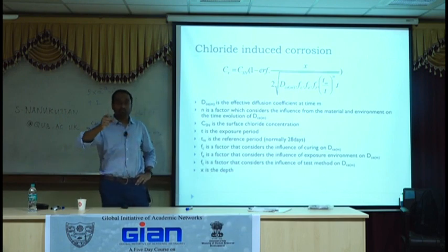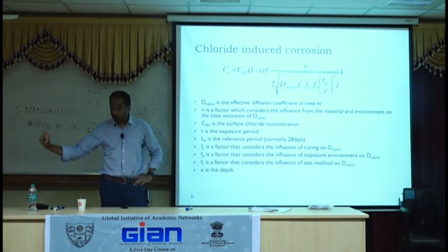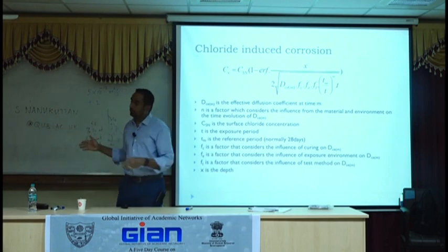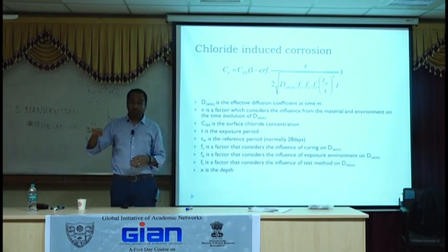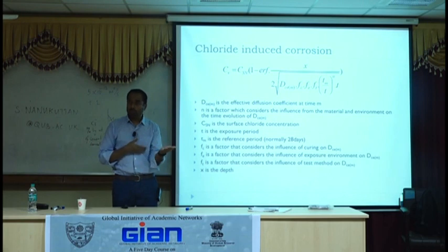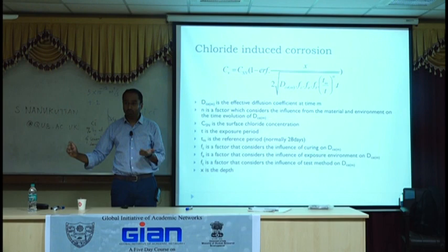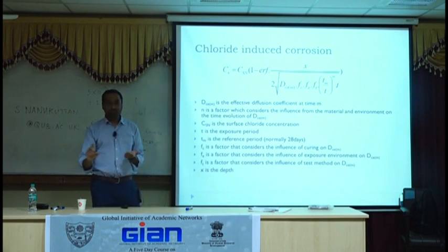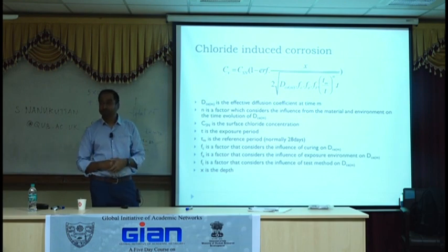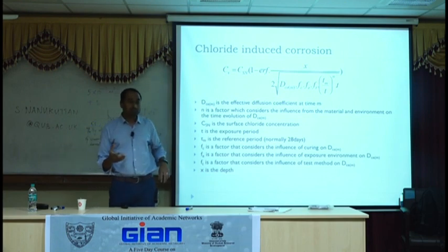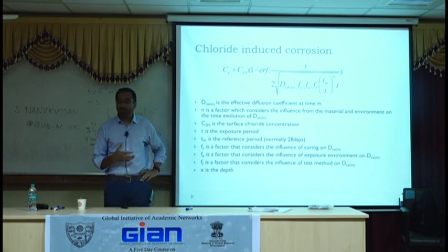But anyway, those silage grass cuttings are low pH, around 4.5. They put it on concrete areas like massive silage pits, which are naturally sloped gently to get the water out. And this water is at pH 4. So when that water slowly drains, and in Ireland it rains all the time, it takes the cement with it. So none of the new cements that we know, if not cured properly, will last.